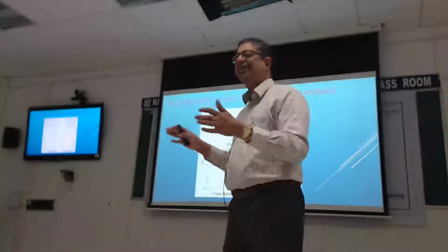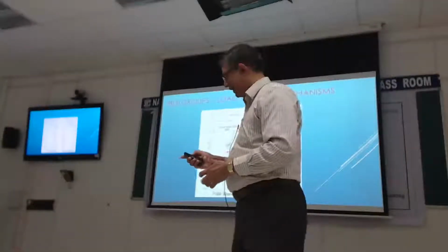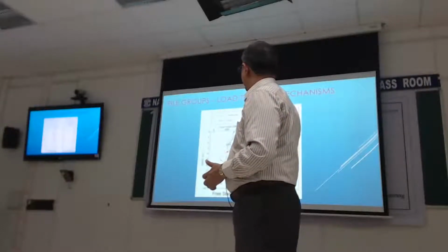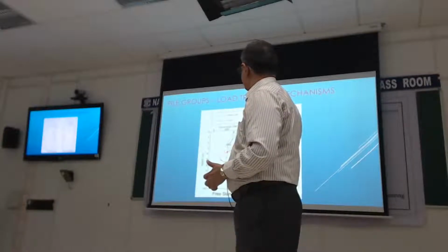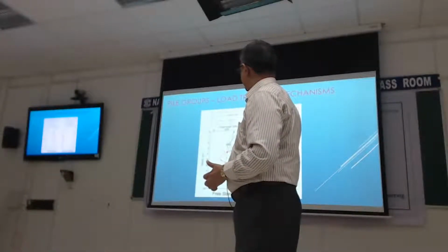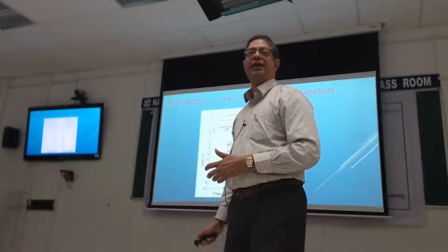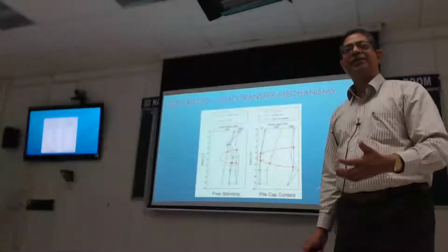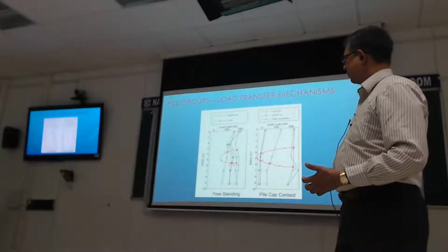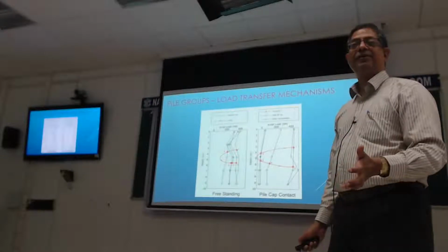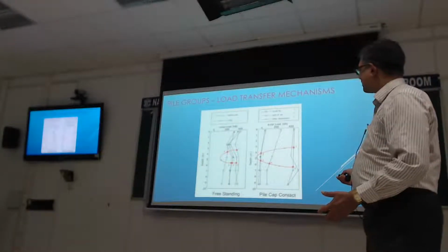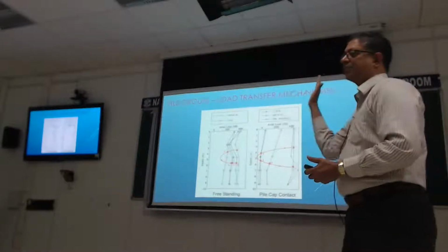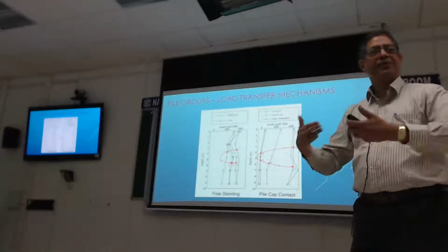Then you shake the soil, you look at it, it's come down to 0.2, where all the loads are dropped to 200. So from 400, roughly, it's dropped to 200 kilonewtons. And then you come to 3, which is maybe 5 seconds after the earthquake, 10 seconds after the earthquake, and so on. So 5 is a long time after the earthquake. So this kind of loop suggests that the load distribution starts there, goes there, and comes back again as the pore pressures dissipate.